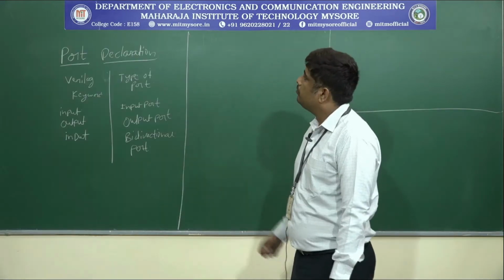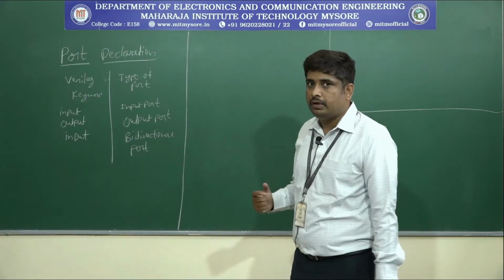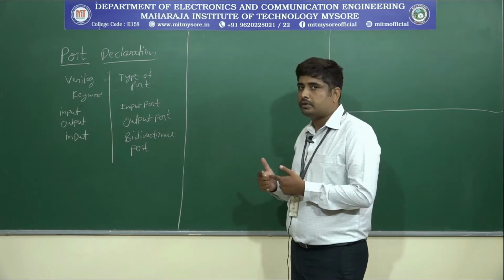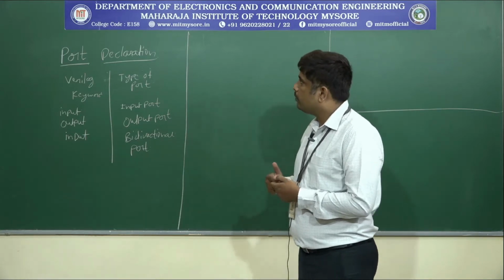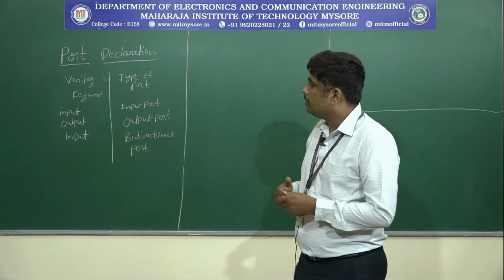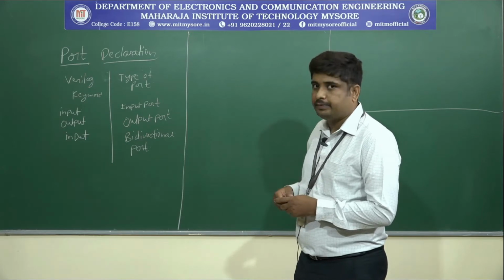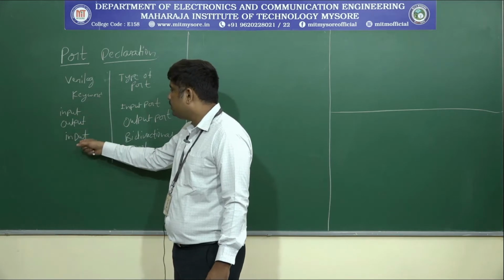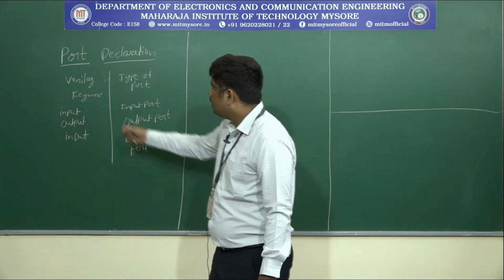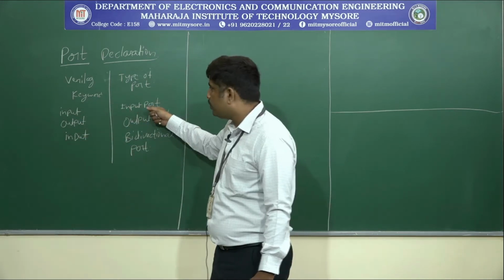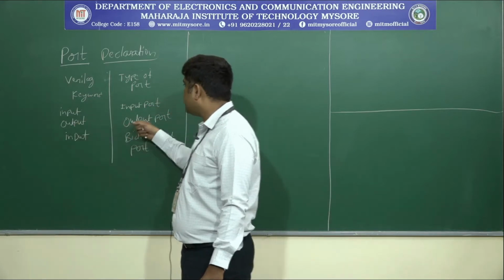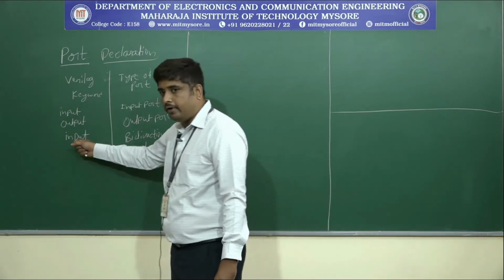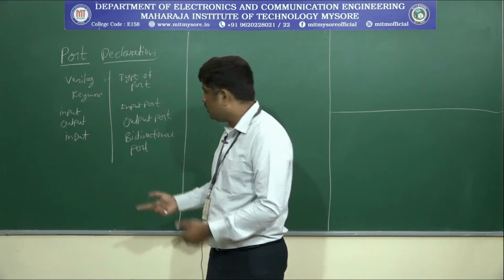Once you mention the list of ports, next we have to declare the ports. In Verilog, ports are classified into 3 types: input, output, and inout. Input acts as an input port, output acts as an output port, and inout acts as a bidirectional port.